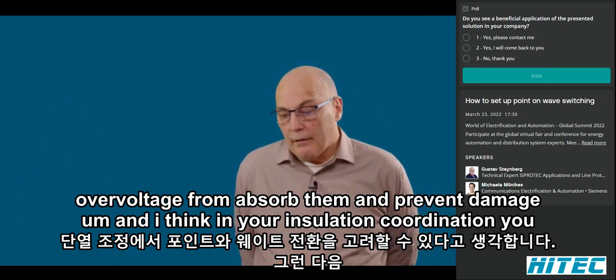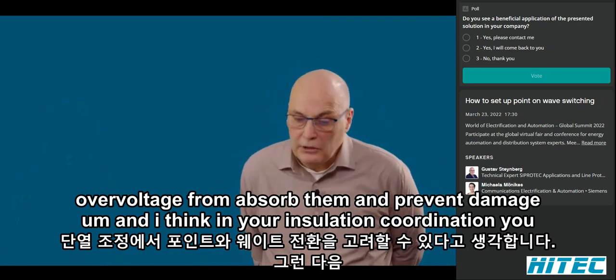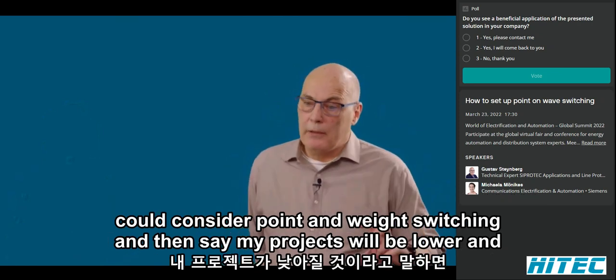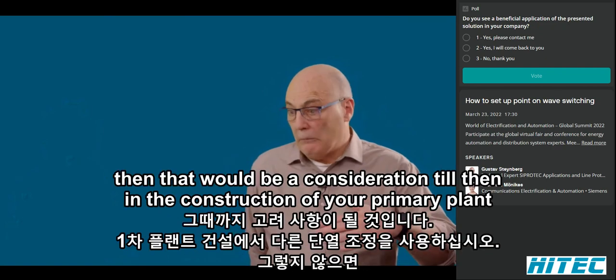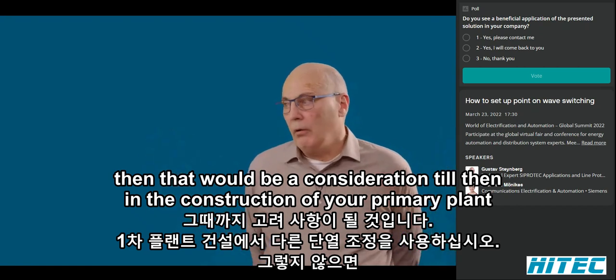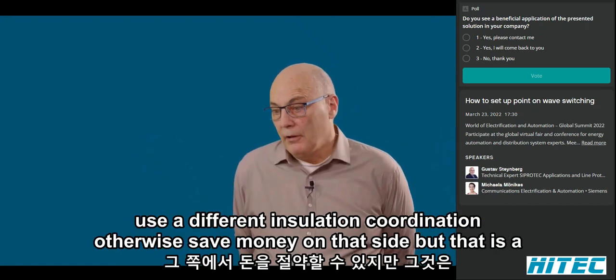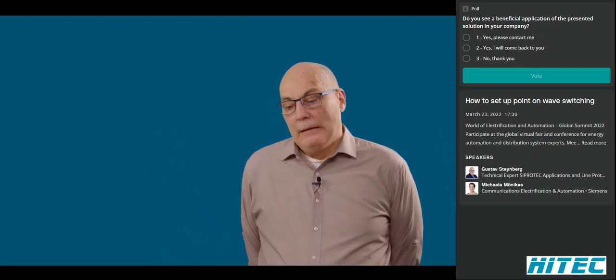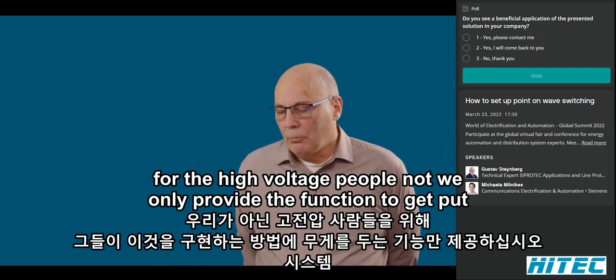I think in your insulation coordination, you could consider point-on-wave switching and say my transients will be lower, and that would be a consideration to then, in the construction of your primary plant, use a different insulation coordination. In other words, save money on that side.